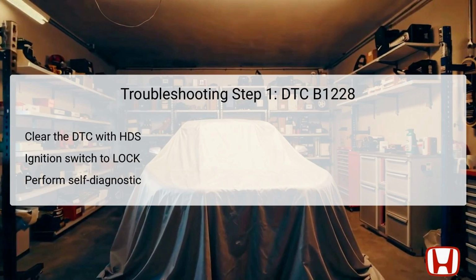Conversely, if no DTC is indicated, it could suggest an intermittent failure that might stem from loose wires or poor connections affecting the outside air temperature sensor circuit.